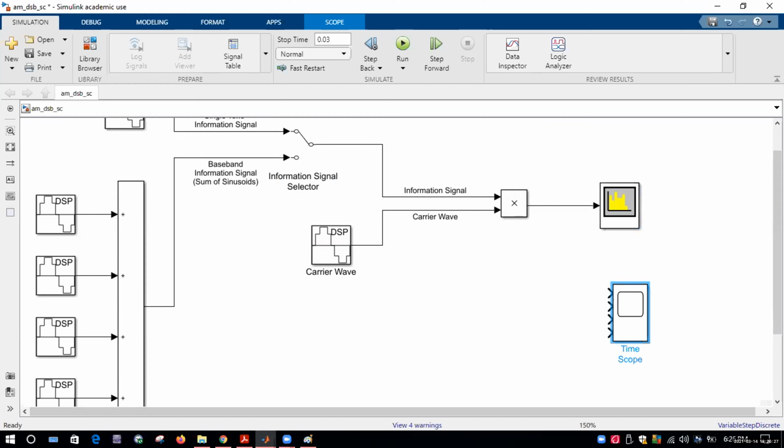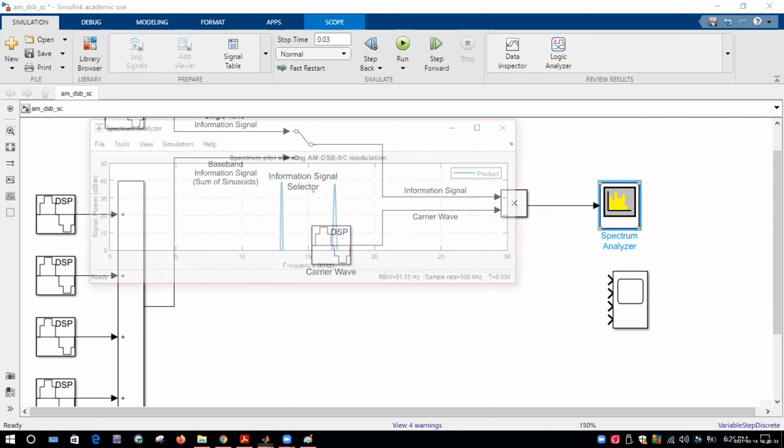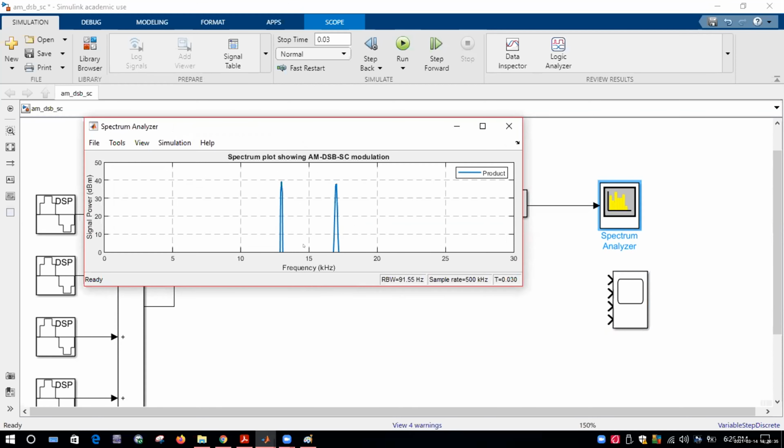If you remember, we also have, I spoke about the spectrum analyzer. So what do you see on the spectrum analyzer? Basically, you see how many frequencies are there in the output, and what is the amplitude of each frequency. This is called spectrum analysis. It means we're trying to identify how many frequencies are there in a signal.